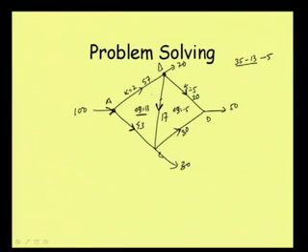So 20 plus 20 is 40, plus 17 is 57. So a total of 57 is going out from this and this, and 57 is coming in. Here also if we check, our continuity condition will be satisfied. Then again if we check here, 20 is coming in, 30 is coming in, 50 is going out, so our continuity condition is satisfied. But the head loss condition again may not be satisfied.